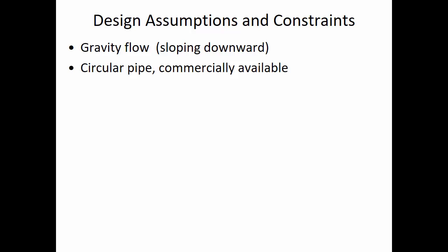It's pretty obvious, but if you think about what that means, sometimes a pipe network can have a circuitous routing. If you're getting from one part of town towards the other, you may have to go around a hillside to be able to get the entire system to flow by gravity. And so the length of the pipes would be greater than if you were taking a straight shot, but then you avoid the need for intermediate pumping stations and wet wells where the water is collected and then lifted and then flows downhill again. So this is a pretty important priority, achieving gravity flow in a drainage system.